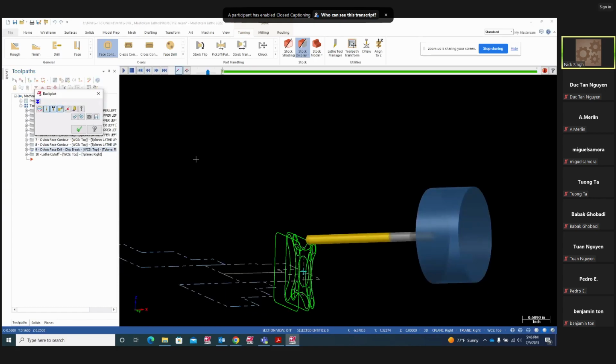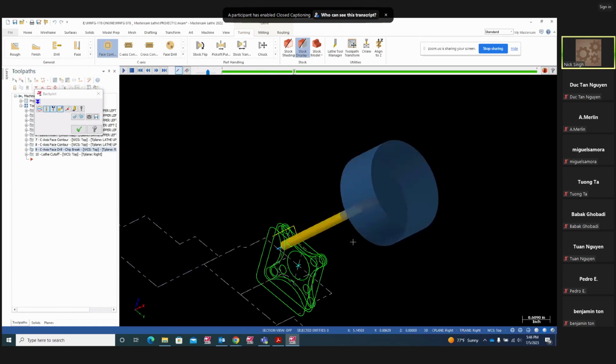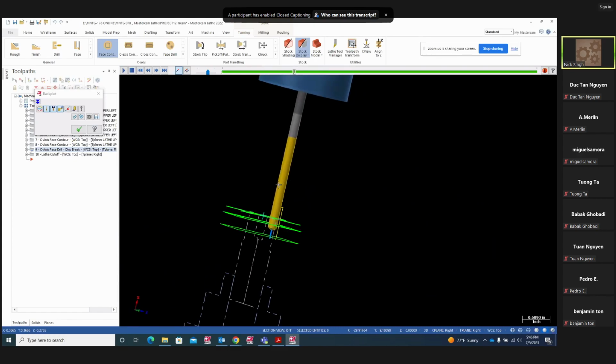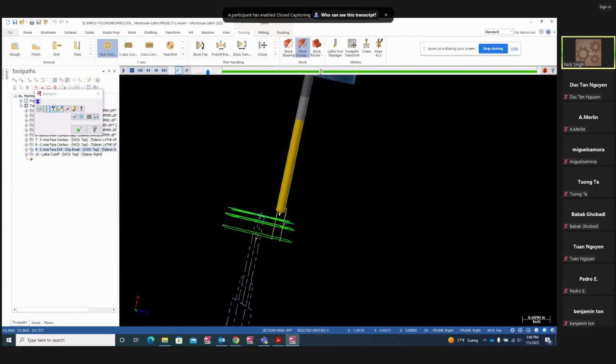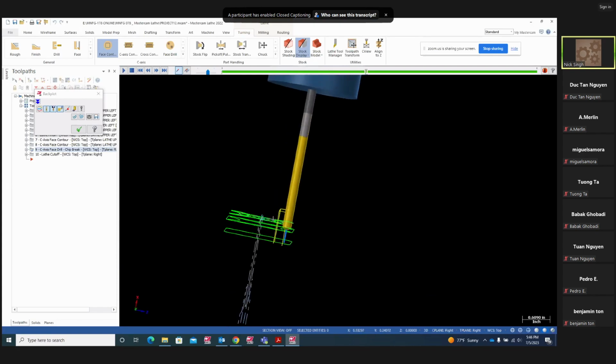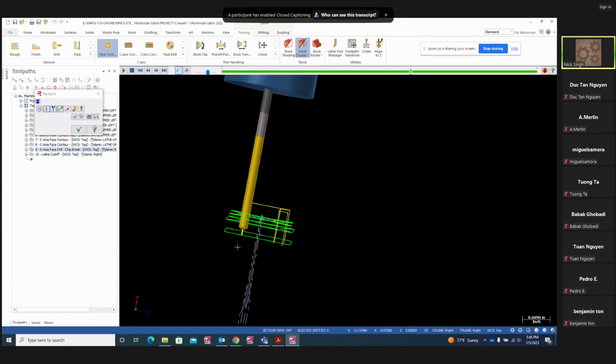It's going to come and drill this, just like a mill, guys. Look at this here, just like mill. Don't get confused. It's not tough, and you're maintaining the same depth, Z minus, from the top. That's my Z0. If you look at the mill, this was my 0, and I'm going from here Z up and Z minus. Look at that.